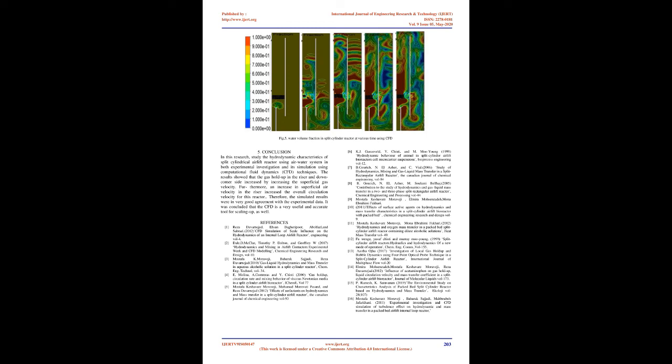5. Conclusion. In this research, the hydrodynamic characteristics of a split cylindrical airlift reactor using an air-water system were studied both by experimental investigation and by simulation using computational fluid dynamics, CFD, techniques. The results showed that the gas holdup in the riser and downcomer side increased by increasing the superficial gas velocity. Furthermore, an increase in superficial air velocity in the riser increased the overall circulation velocity for this reactor. Therefore, the simulated results were in very good agreement with the experimental data. It was concluded that CFD is a very useful and accurate tool for scaling up, as well.